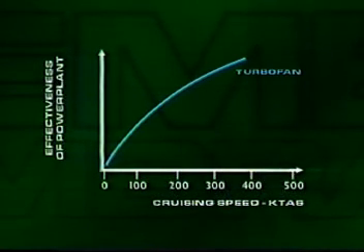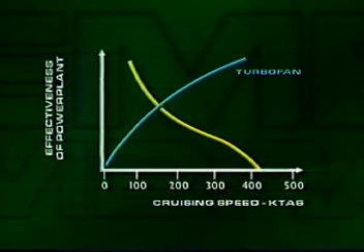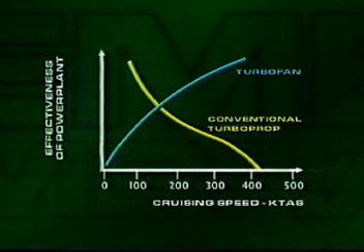The propulsive efficiency of the conventional turboprop decreases substantially as airspeed increases above 300 knots true airspeed and is null around 400 knots true airspeed. While the turbofan engine produces power efficiently up to and above supersonic speeds, it is clear that at the high speeds required for transport aircraft, the propeller is quite unsuitable and explains to some extent why they were offset by the introduction of the turbofan engines.